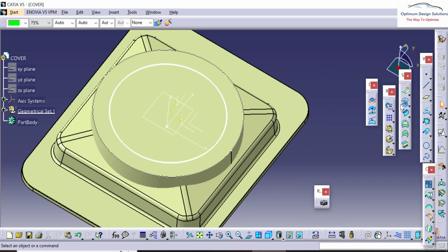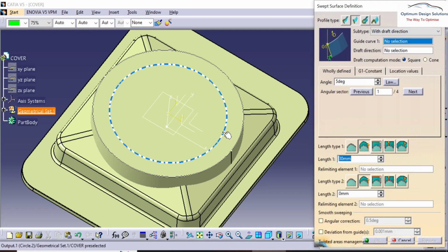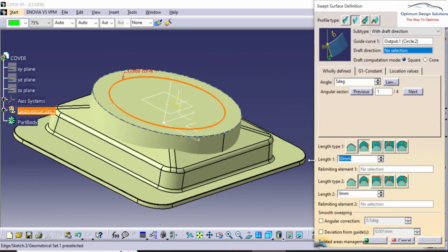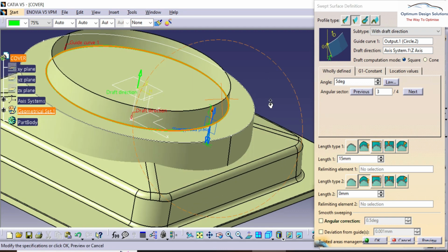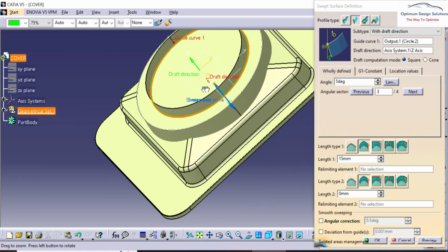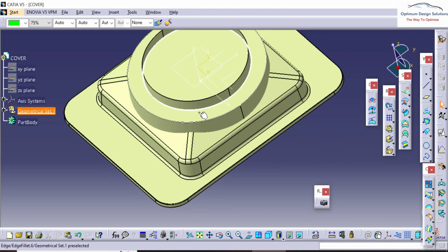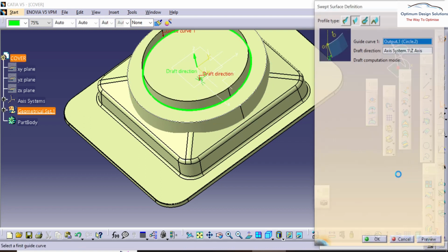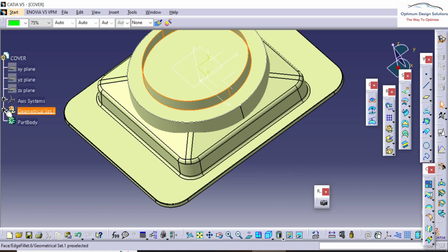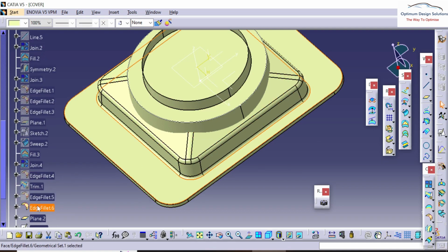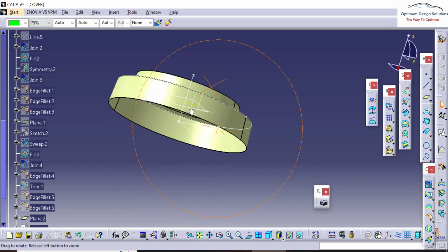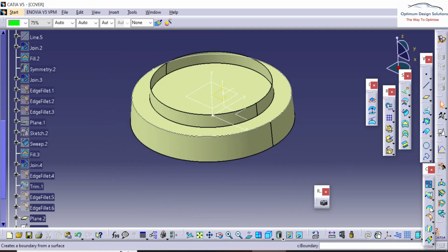In the same way, we'll create some depression or some extract surfaces at the top side also. And for adding the air inlet or exhaust ribs, we'll use the Boolean operation also, so this tutorial will be a mix of advanced surfacing and advanced Boolean operations or part design also. In the same way we'll close the top side surface also. We'll hide this to get a proper visualization.